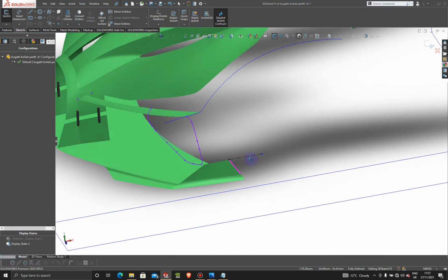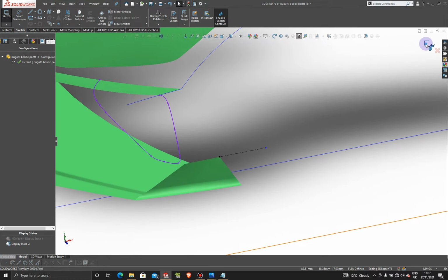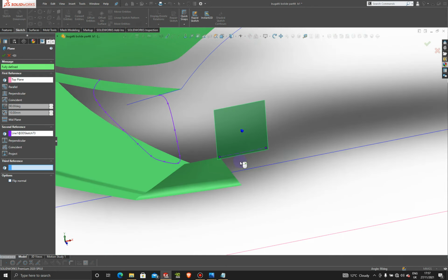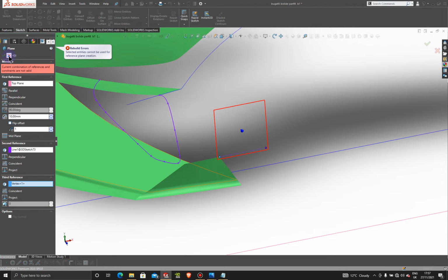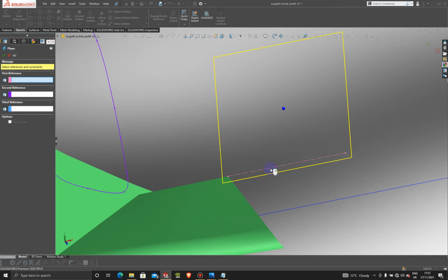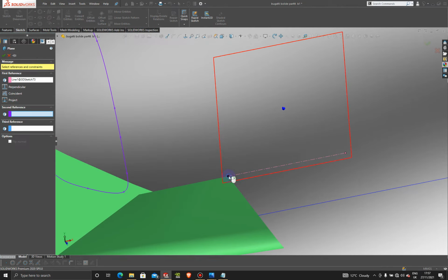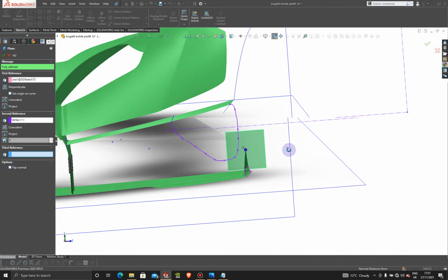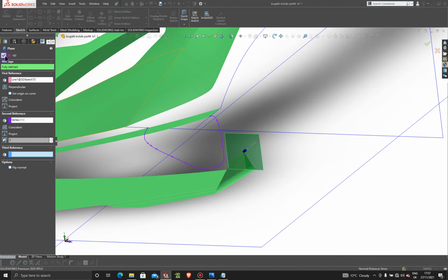and press escape on your keyboard, and then exit from here, and then let's put our plane on that sketch which was made. So click on the line first, and then click on the point. Well, we clicked on the different point. So plane, line, and point. That's it. That's our plane right there in the perfect position. And then press OK.